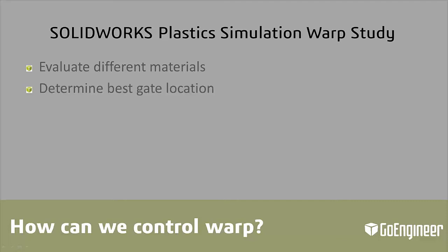So you have the ability to go in and try different gate locations all around your part without having to go through the whole mold process and molding them. You can do all of this ahead of time to find the best gate location to control your warpage to start with.